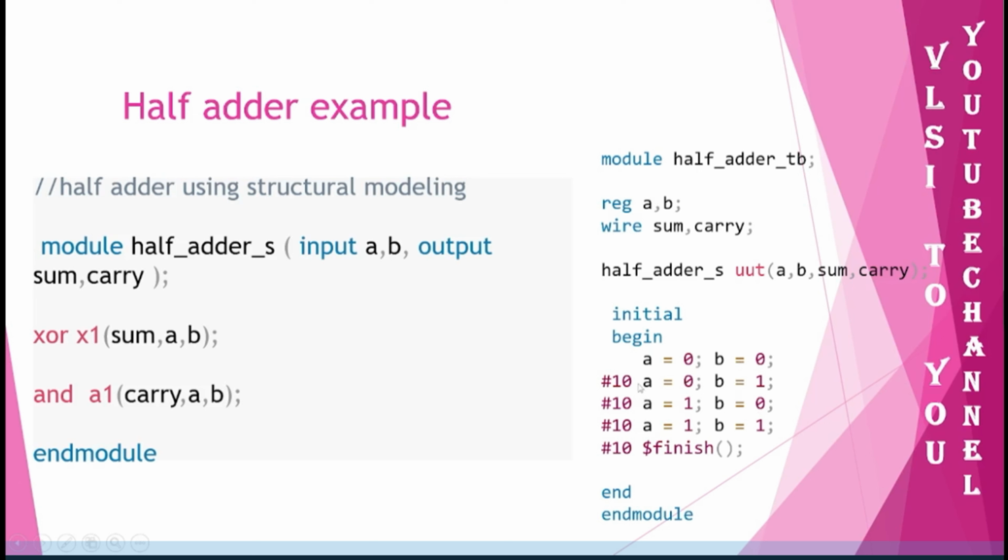For every scenario I am giving some time, 10 time units of delay, so that you can see the output. When you are creating any monitor, $monitor or anything, you can see the output if you are giving some delays. It's okay if you don't give a delay also, that is fine, but at least a #1 unit delay is better. And then $finish. Since all the values have been passed, I am giving this $finish and then endmodule. That's it.